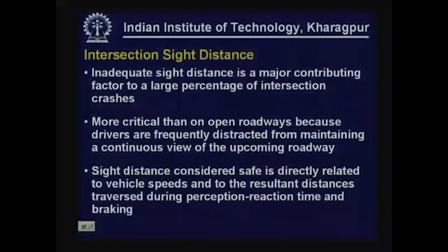One should remember that intersection sight distance is more critical than on open roadways, because drivers are frequently distracted from maintaining a continuous view of the upcoming roadway. Therefore, intersection sight distance becomes more crucial.